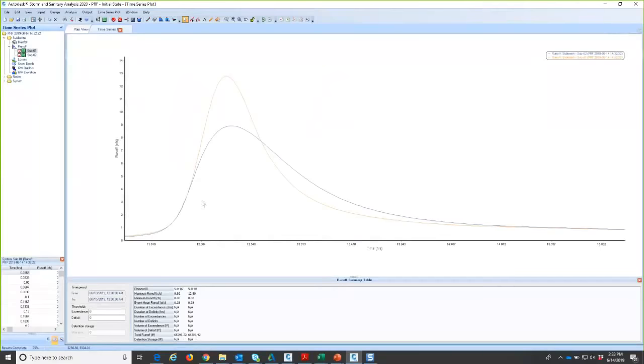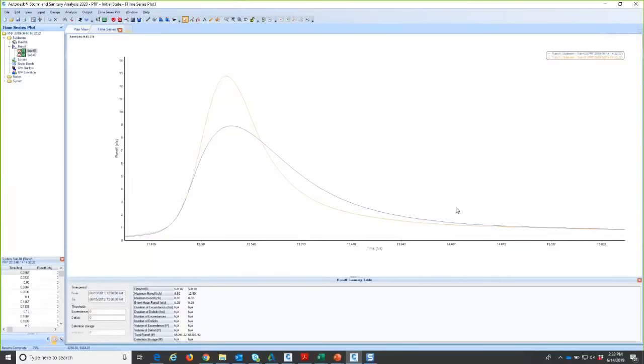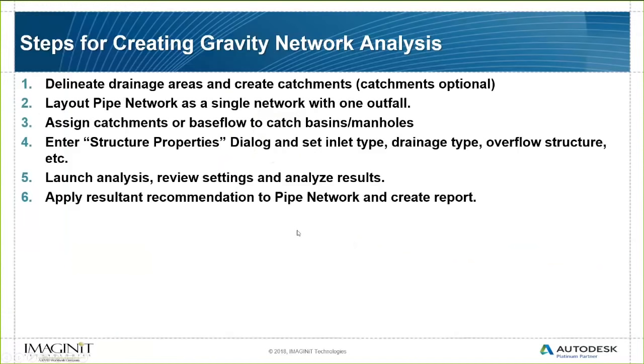So say you run this analysis, you are certain that your time of concentration is accurate and your ground cover is accurate, and then you compare that to flow meter analysis and find out that your hydrographs do not have the right shape. It could be a matter of the peak factor needing to be adjusted.